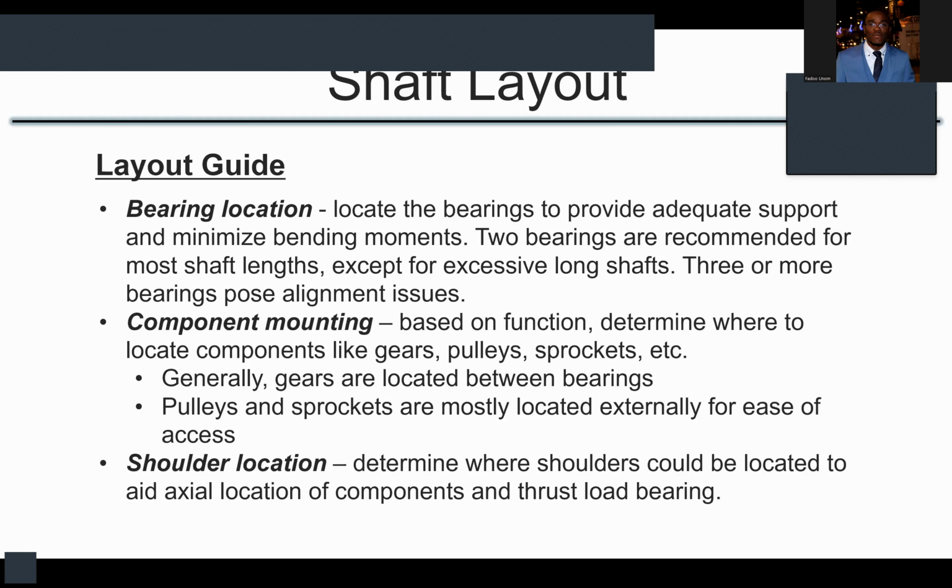For something like pulleys, they need to be located externally for ease of access. Okay? Your fitting of the belt. If you locate your pulleys within your bearings, it's going to be very, very difficult to change your belt if your belt becomes slack and you want to adjust it, tighten it, or if your belt develops a problem. So usually you don't.